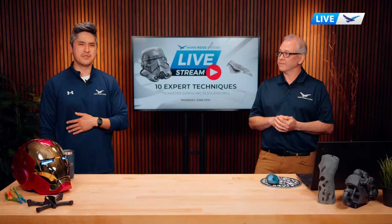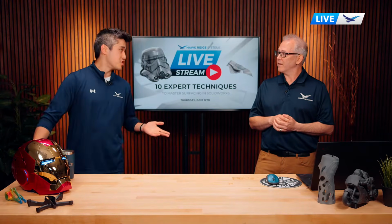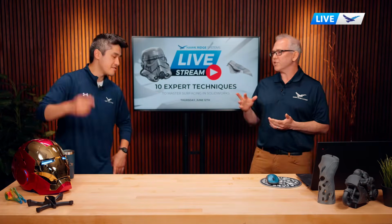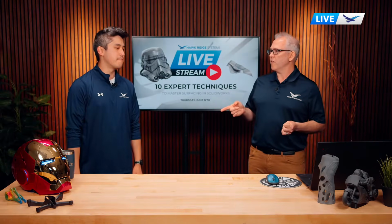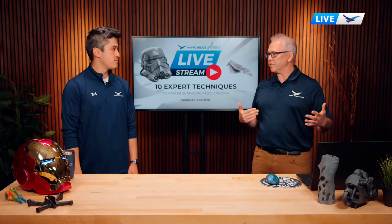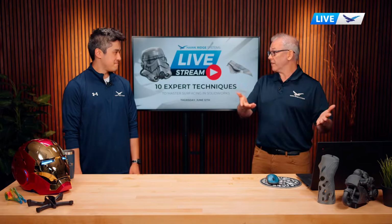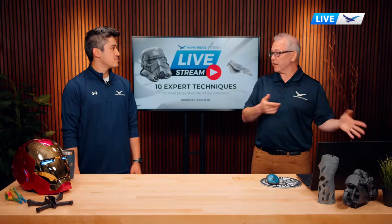It's kind of a weird hidden thing. I think you could put a little checkbox in there. I mean, it's not really necessary, but it's kind of two features in one. I'd say that the move body feature is similar, where there's a copy checkbox. And as you check that, it changes it to a copy feature. You can copy it in place just like copying a surface. You can keep it exactly where it is, or you can move it and copy it at the same time.